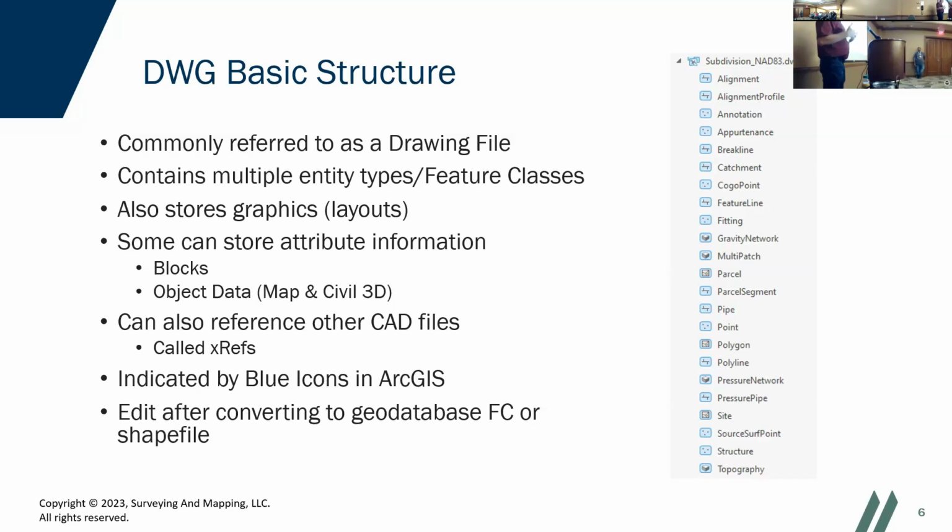Okay. And blocks have been around for as long as I know. Back in '12, I used blocks, and I think they were back even before that. So we can read those into GIS, and we bring in the point layer with those blocks, and all those block attributes are going to come across as well. Sad thing is, I think there are a lot of CAD users nowadays that don't even know how to create a block or what one is, but it is a way to do it.